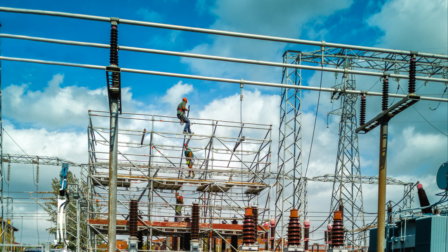In our towns and cities, there are electricity substations, which are called primary substations. These distribute the power at high voltage to secondary substations, which then transform the voltage down even further to our homes, businesses and factories. Some of these cables are overhead with pylons or wooden poles holding them up, and some are buried. Finally, there are the cables that connect to our homes and businesses at more familiar lower voltage levels. All of this infrastructure makes up the distribution network.